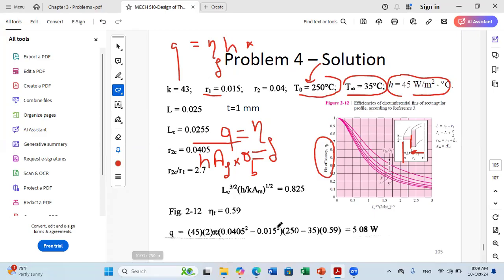What do we mean by the frontal area of the fin? This one, meaning the area through which we have the exchange. Whenever you have a circular fin, I will draw it for you here from the top, in a top view. This is the frontal area from the top, but pay attention, you should consider both the upper and bottom area, so it's 2 times this area.